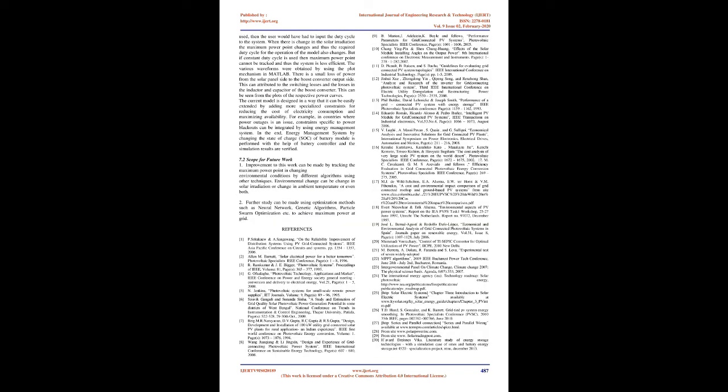Chapter 7. Conclusion and future scope. 7.1 Conclusion. In this thesis, a Simulink implementation based on the five-parameter diode PV model has been constructed. The effect of varying model parameter values and the effect of different solar light intensity and ambient temperature has been demonstrated. Maximum power point tracking using the Perturb and Observe algorithm has been implemented. Some weaknesses with this tracking method have been exposed, and these include wrong reactions to changing inputs, slow voltage reaction, oscillation around MPP, and a limited amount of perturbations per data point in these simulations. The maximum power point tracking implementation successfully keeps the voltage close to the maximum power point most of the time.